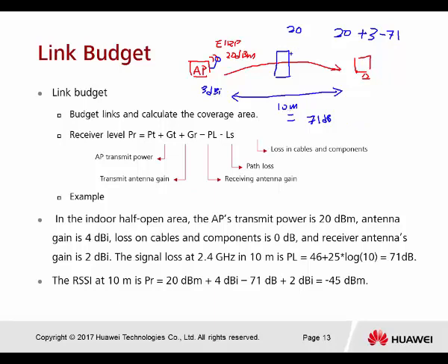And don't forget the obstacle, how much loss will it cause? Giving the example, this is 8. Anything passing through here will lose 8 dB. So now I'm going to minus 8. Then you get the answer. 20 plus 3 will be 23, then minus these two, 79, so you get 56 in dBm. When you're using scanning software on your PC, you'll notice this is the signal that you receive. So this is further proof why the signal that we receive is always negative.